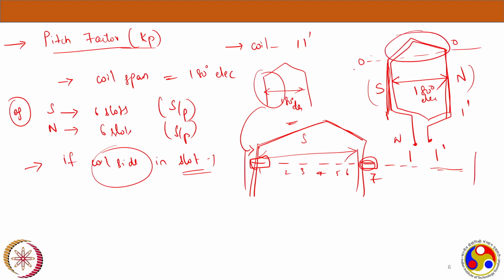That is usually what we call an overhang. That is not a useful part because it does not come under any pole in the machine. It's just a base part, the overhang. That's why people try to reduce that overhang so that we can save the copper winding. That's another discussion, but here you understand, right?